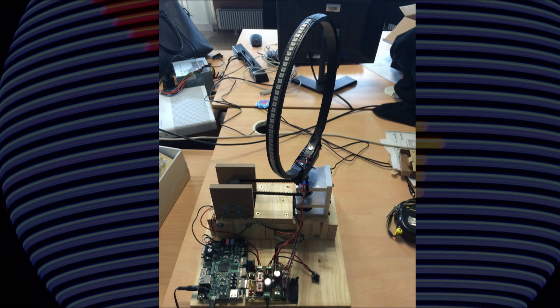As the last version of the globe used a slower LED strip, we had another LED strip on the other side of the ring, which displayed the opposite column. The idea was to double the frame per second rate without changing the rotating speed. As you can see, the LED strip on the other side is hidden under adhesive tape and is currently kept only to balance the rig mechanics.